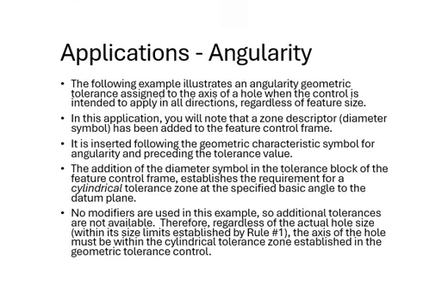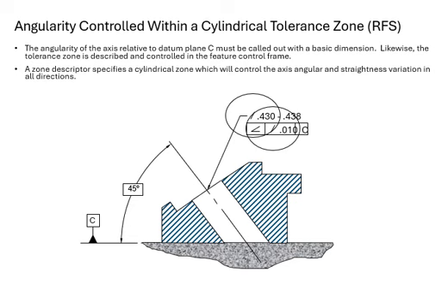All right. Okay, now we're getting into our example. For the application of that method, we're going to measure the angle from the axis. So here is your hole, and here is the axis, and here is your part. And there's your datum or reference plane, which is C, and we put it in a control frame like that. The datum reference plane is also determined by a tool, and we call that a gauge or surface gauge. You stick it into contact with all the high points on that part, okay?